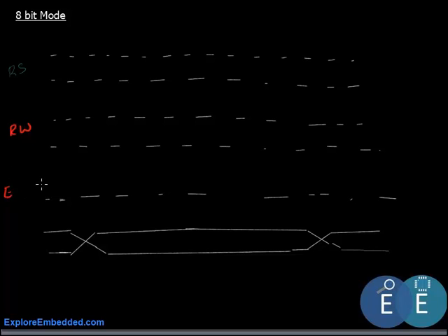Now before we send a command or data to the LCD, we should ensure that, the enable is the gate for sending commands or data to the LCD. So even before we give the enable pulse, the register select, read write and the data lines should be set up.